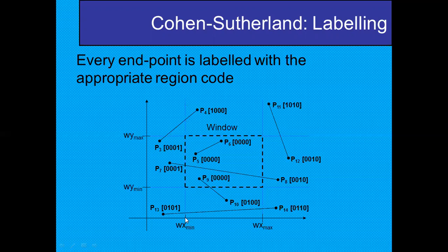Okay, so first we will consider what is the value from here. Suppose this is 5. Then from the origin with the help of the scale we will measure 5, and here we will put the intersection point, a dot point, and use a right angle triangle. You can use your triangular shaped set square so that you can draw the perpendicular line. So with the help of this 5 units from the origin, just put a point here and draw the perpendicular straight line, 90-degree.